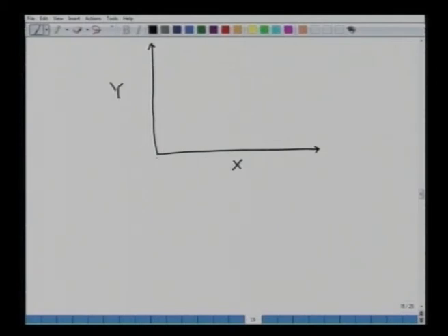All right, so if you plot on log scale, 100, and here we have 1000, 0.6 for y, the lowest units, and here we have 10. So essentially, if you plot this data, you can fit the Freundlich isotherm. So log y equals log m plus n log x.